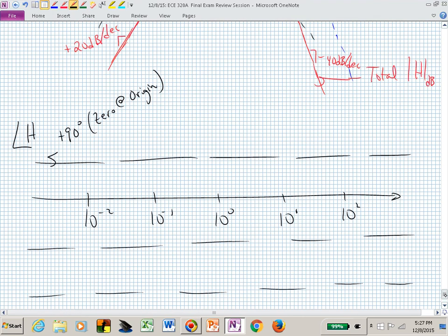Here's our zero at the origin. We have a phase change due to the pole here at 0.5, and that will be contributing phase over a 2-decade span, and it would be this. There's the change in phase due to the single, linear pole at 0.5.